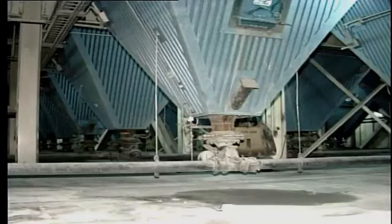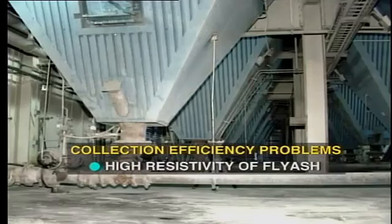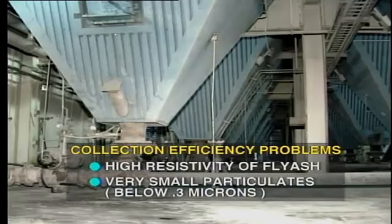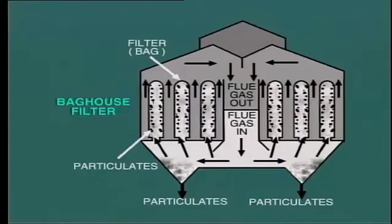The main problems causing loss of collection efficiency in a precipitator are high resistivity of the fly ash as a result of burning low-sulfur coal, and the existence of very small particulates below 0.3 microns in diameter. These problems can be overcome by installing a fabric filter instead of the ESP. The fabric filter simply blocks the passage of particulates and therefore is not affected at all by the resistivity of the fly ash. In fact, its efficiency of particulate removal is greater even than the ESP.